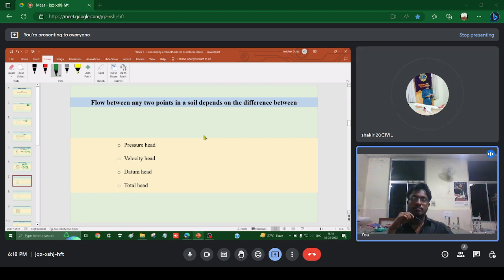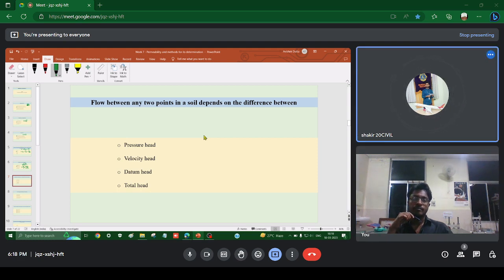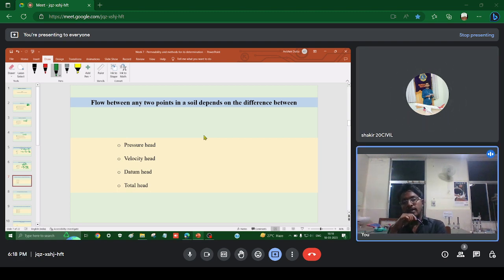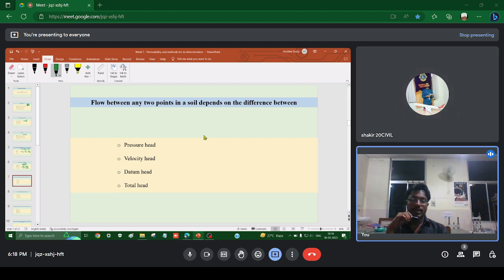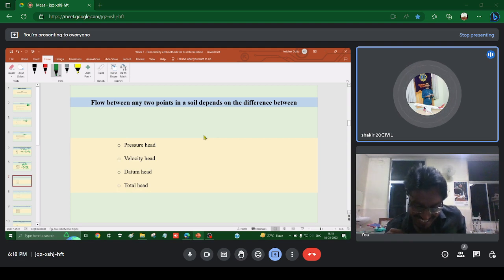This is a simple, basic question. Two points in a soil, the flow depends on pressure head? Think again. Because of what you have said, I'll say both are applicable. Total head. You told us, sir, both are applicable, datum head should also be considered.